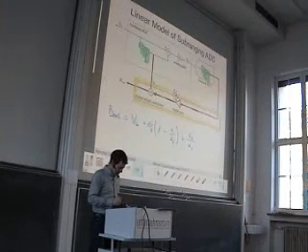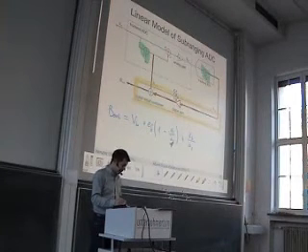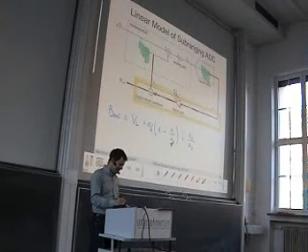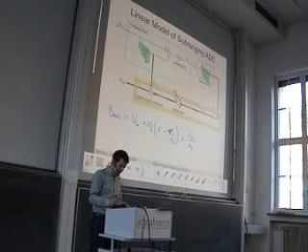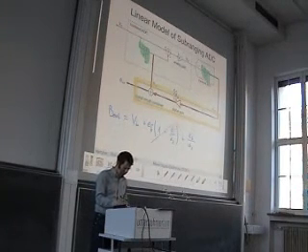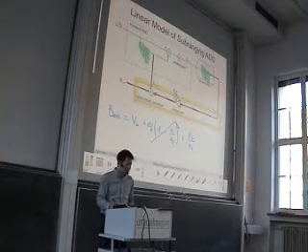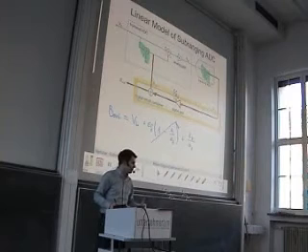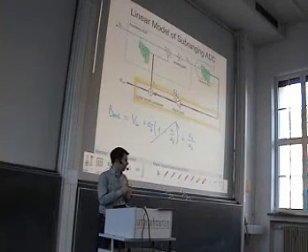Well, indeed, if we say the A, the analog gain, and this digital gain is the same, then we have a factor of 1 here, so we have 1 minus 1, and this term here cancels. However, this cancels only if the A and the AD is exactly the same.